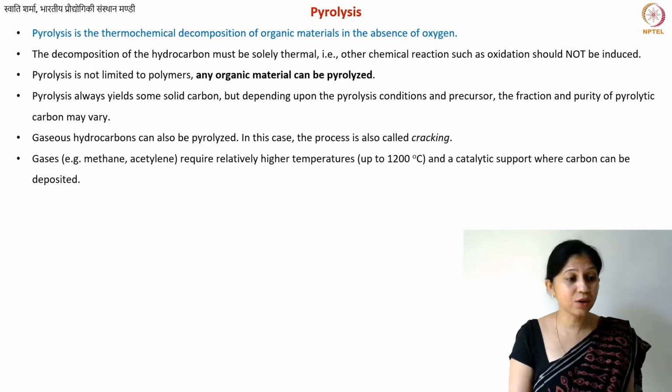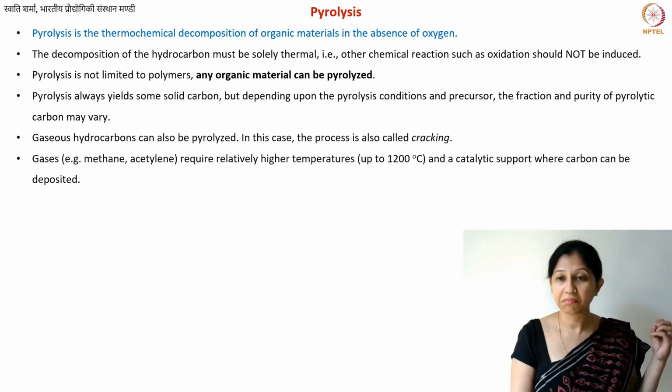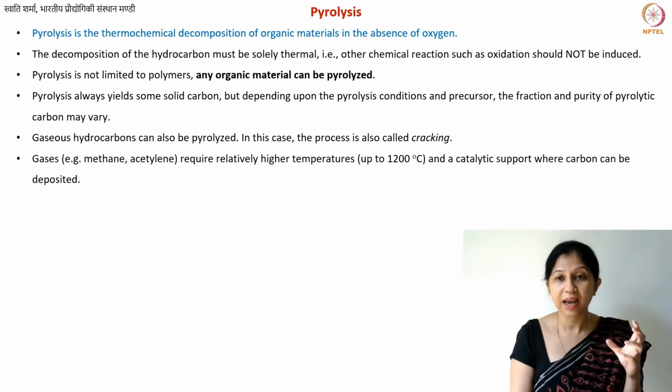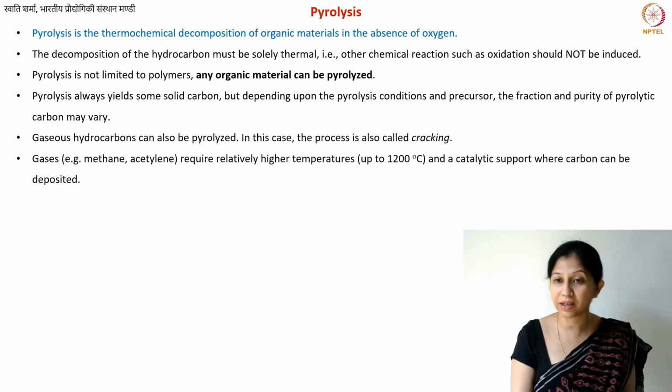Okay, so what we can do now, in a chamber, we flow one hydrocarbon, typically with a carrier gas, because you want to also control the concentration of this hydrocarbon. So you'll have a carrier gas, and obviously the carrier gas should not be participating in the reaction, so that will be an inert gas. Also, if you want the carrier gas to somehow induce catalytic activities, then you can choose a different carrier gas, but typically you will have one hydrocarbon that flows inside your furnace.